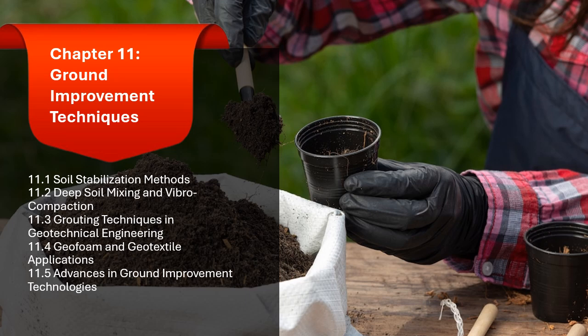1. Cement grouting. Cement grouting involves injecting a cement slurry into the soil to form a solidified mass that increases the soil's strength and reduces its permeability.